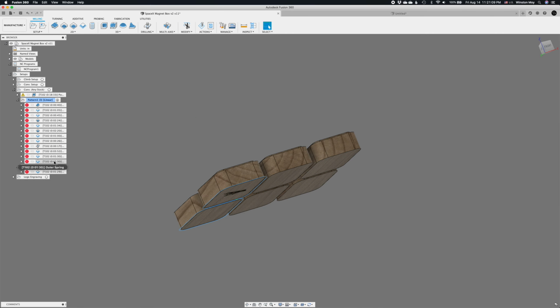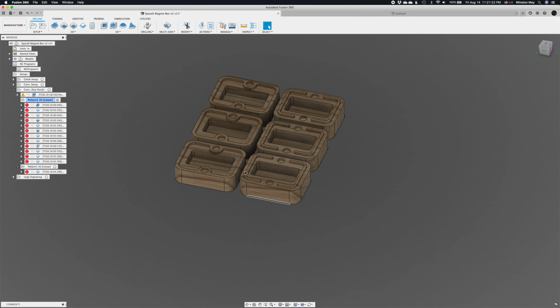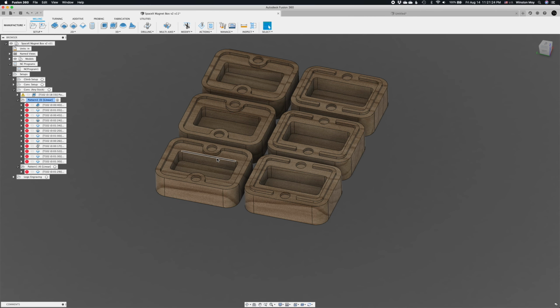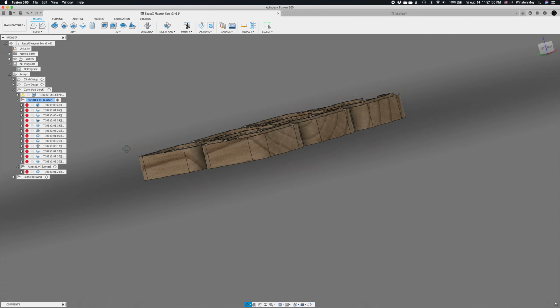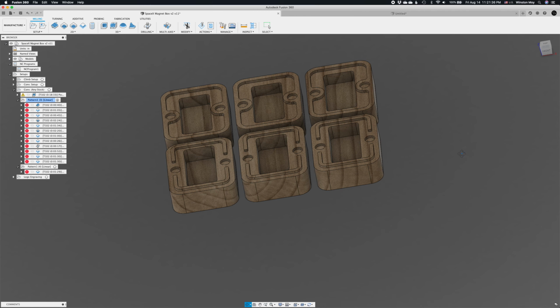That finishing toolpath is going to be, at least in here, a little slower than the contour toolpath. Smaller chip load, slightly finer finish on the walls. But you can play around with that depending on what diameter cutter you're using, how many flutes you have. The more flutes, the faster you can finish. So small things like that you can play around with. But for me, I'm just using an 1/8 inch down cutting end mill, and that's it.